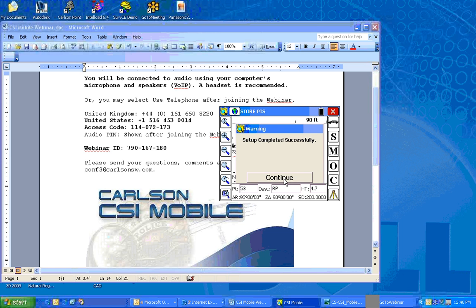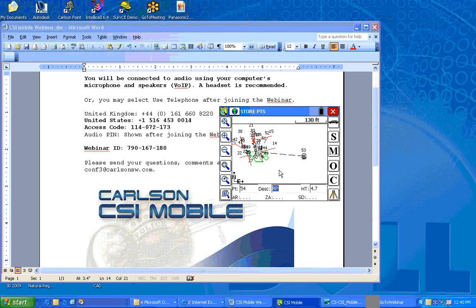So, yeah, that's right. It was 200. So how about that for a nice little warning, that your backside distance didn't match up to your foresight to the move up. But that's a valuable thing. So here you are on your new point, ready to gather other shots in.